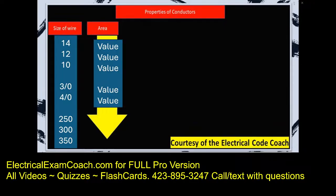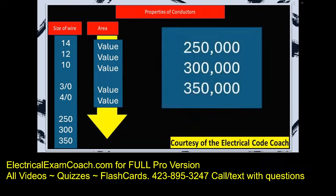So don't worry about if it's solid or stranded. Just go over to the circular mils. Make sure that you're in the area section under circular mils, and you'll find your value. You'll notice when you get down to 4/0 that the values stop. The reason is because the left-hand side of this table, the 250, 300, and 350, are already showing you what the circular mils are in KC mils. So we have 250,000, 300,000, 350,000. Once you get past 4/0, you're going to get into 250, 300, 350, and all you have to do is add on the 3 zeros.